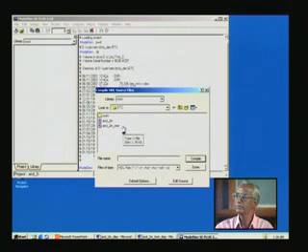So it is enough if you just compile this test. It will automatically go to this design and do the compilation. You don't have to do it afresh. So if you just double click this here or single click, it will appear here, and then use compile. Had you double clicked, it would have started the compiler straight away. That will be a shortcut for you, you can adopt later on.